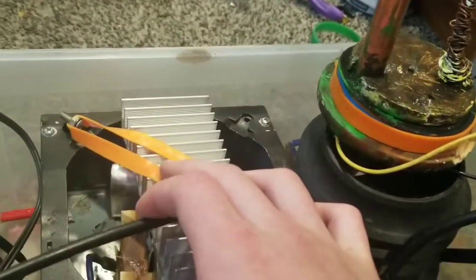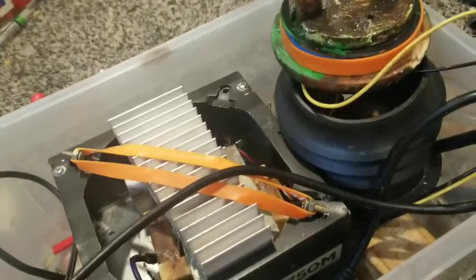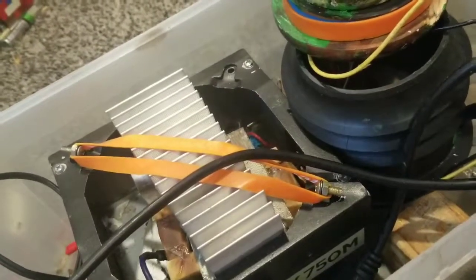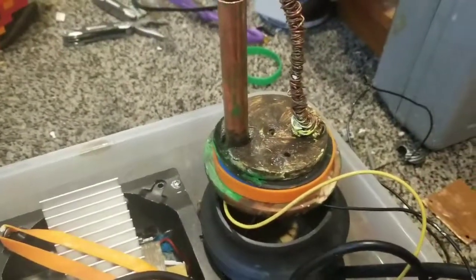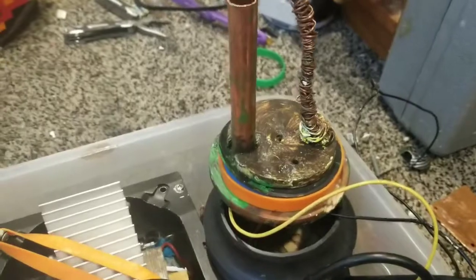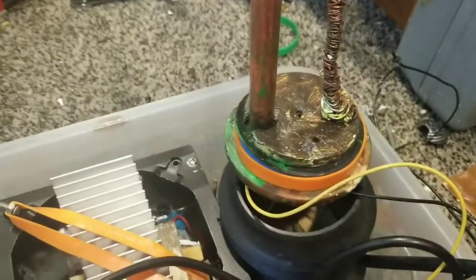And high voltage is obviously very dangerous. Don't mess with it unless you have some experience. And one important thing about high voltage is that you always work with one hand behind your back, so that you don't grab something with two hands and electrocute yourself to death. Because if you grab something with two hands at the same time, it goes right through your heart. But if you're only using one hand, the worst thing that's going to happen is you get harmed on the hand or something. So yeah.